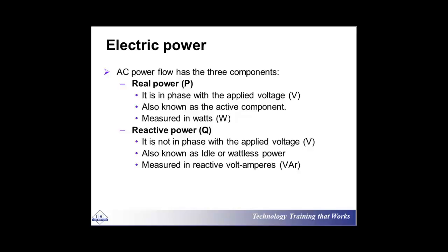Okay, I'll give you one hint. The rating of the transformer is normally given as MVA or KVA, and that MVA and KVA, for your information, is the unit of measurement for S. Therefore, the power company has already paid for S. In other words, that power company has already paid for both P and Q. However, when they give that power to your home, you are paying for P, and the energy in watts is based on P.